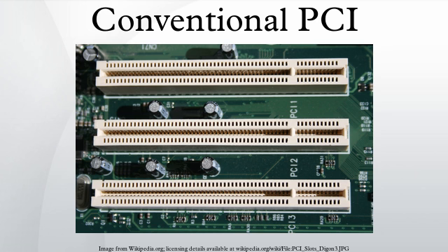Targets which have this capability indicate it by a special bit in a PCI configuration register, and if all targets on a bus have it, all initiators may use back-to-back transfers freely. A subtractive decoding bus bridge must know to expect this extra delay in the event of back-to-back cycles in order to advertise back-to-back support. 64-bit PCI.